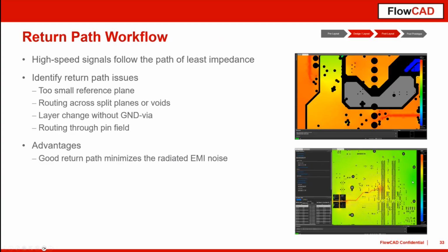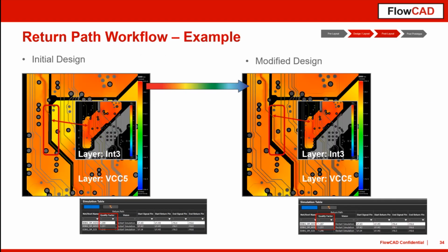Here in these images you can see, okay, we have a nice return path directly below our signal traces because we have a complete reference plane. But once we have such holes in it, what happens with our return path? It searches some vias to create a closed loop, a current loop, and you never know where this return path now goes, where the current goes through your design.